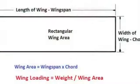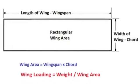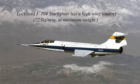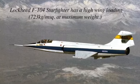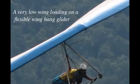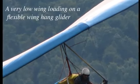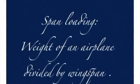Wing loading and span loading. Wing loading is the loaded weight of the aircraft divided by the area of the wing. An aircraft with low wing loading has a larger wing area relative to its weight as compared to an aircraft with a high wing loading. As the wing loading increases, the takeoff and landing distances and speed increase, whereas the ratio of the weight of an airplane to its wingspan is span loading.